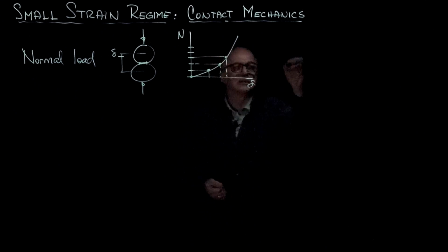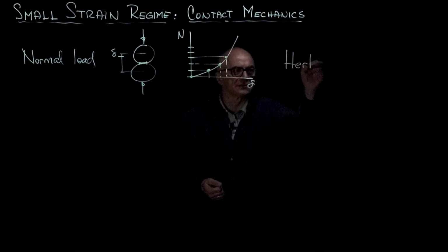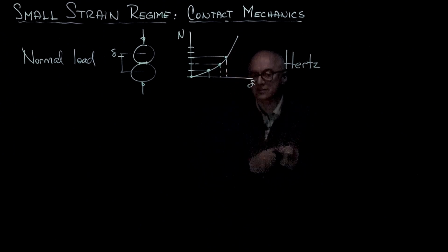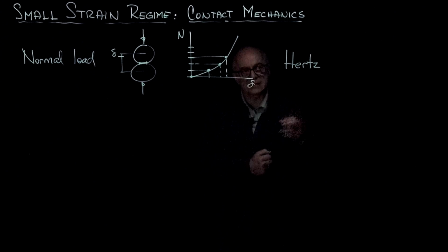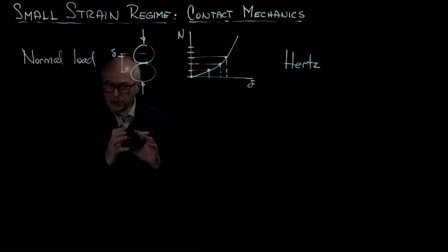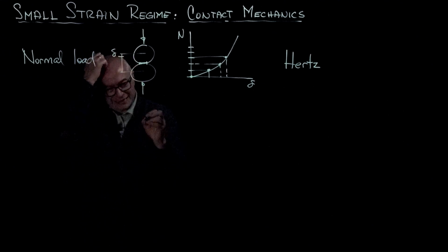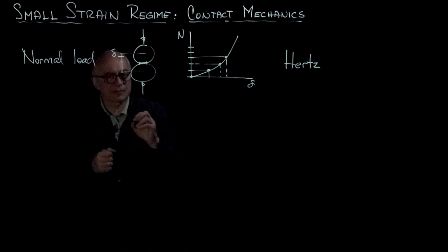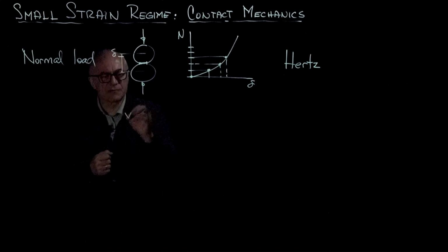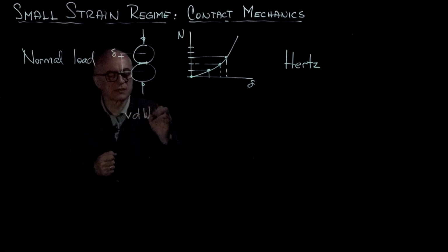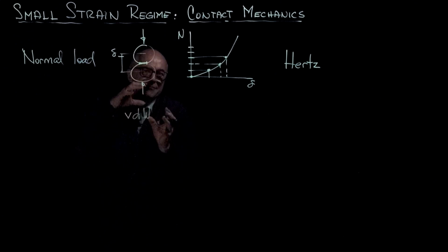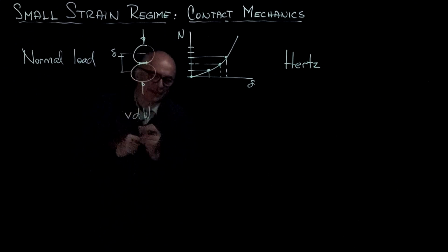This is called Hertzian contact, and was studied by the same individual who actually proved the existence of electromagnetic waves, a great scientist in the 1880s. For smaller particles, there may be attraction forces. Go back and look at the interparticle interaction forces. There may be van der Waals interaction forces, and that additional force makes the particle get a little bit flatter.